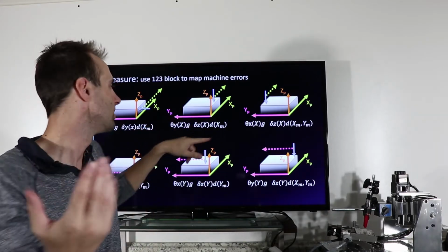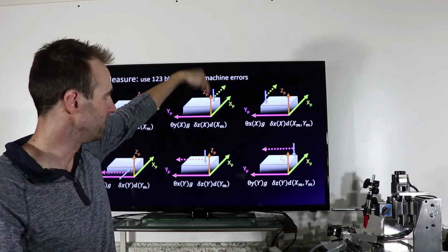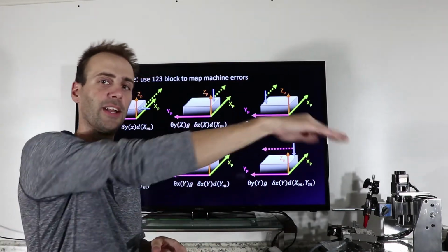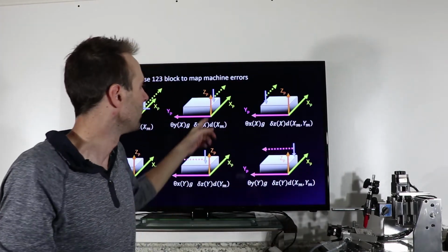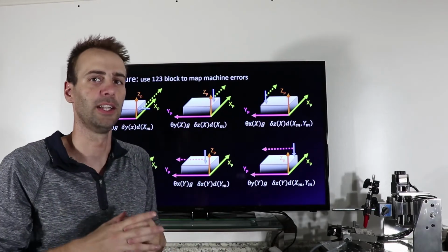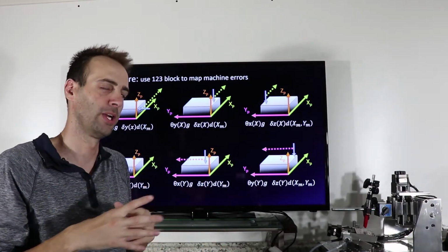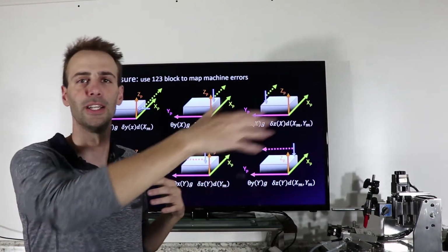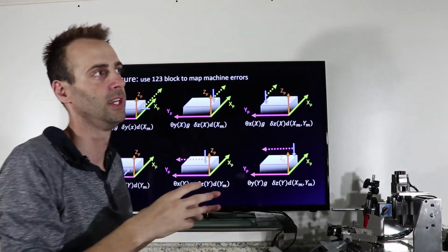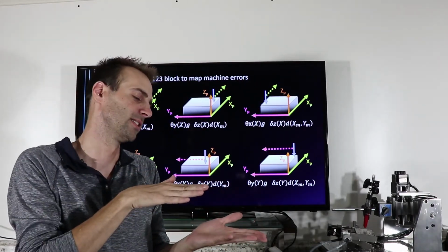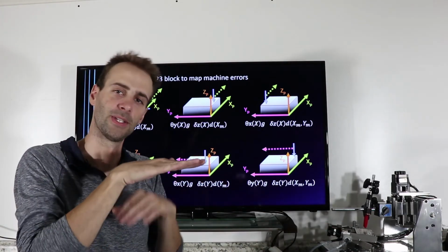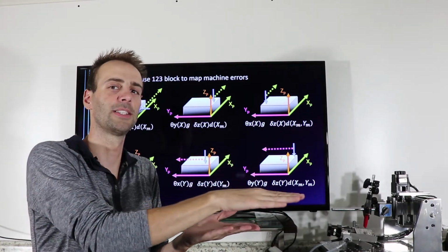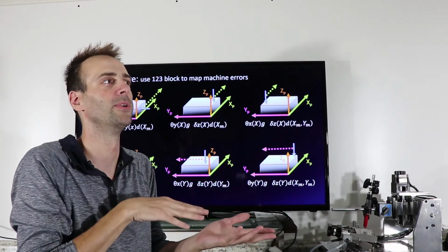But then if you take the residuals, that's the dynamic error in the z direction as a function of my x-axis, right? And that's like this hop and skip. What I'll say about that is ignore the high frequency stuff, because that's generally not repeatable. And when you take those measurements, do it 10 times and then average them, because, for example, if you had 10 bearings underneath on a perfectly flat surface, but the bearings weren't round, sometimes it'll rise, sometimes it'll drop, and that won't be repeatable.